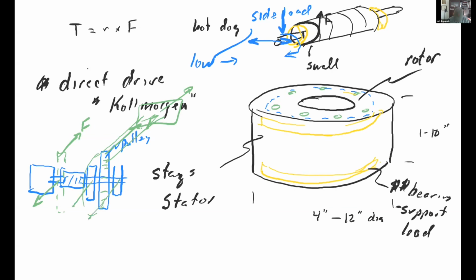This bearing in the motor here is really just designed to hold the motor in place. It's not a very useful bearing. So beware of that. So if you want to move loads that are large inertia, you kind of have to do all this lineup, and there's a bunch of parts that you have to buy.